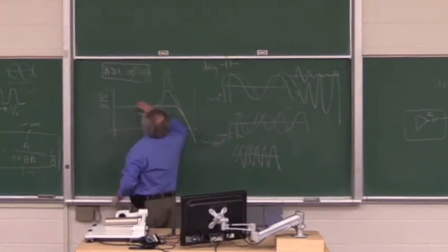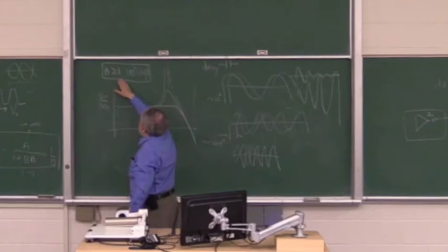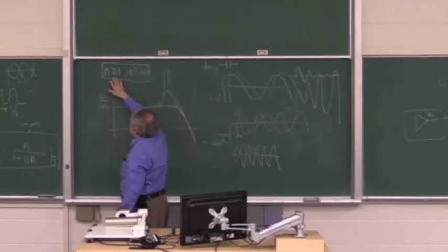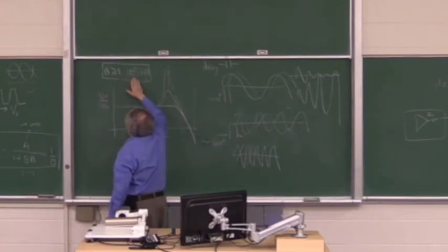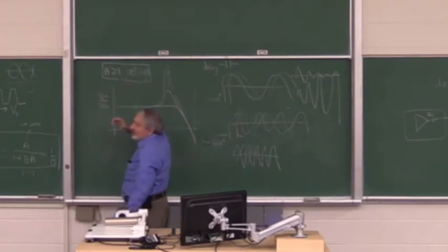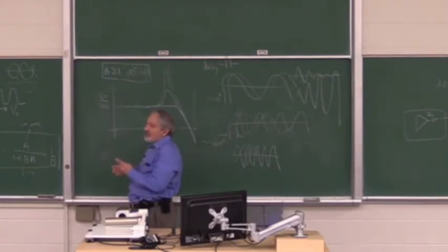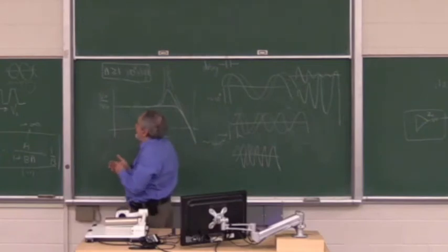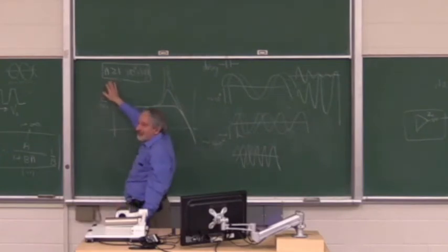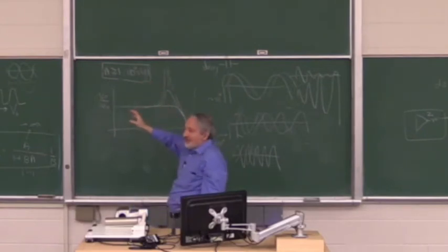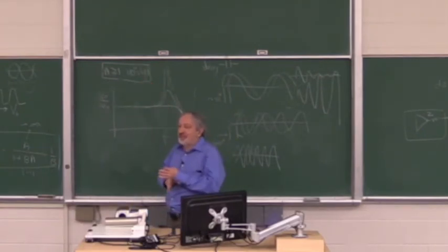So anything above that, if A is bigger, or even if A is much bigger than 1 and the phase shift is less than 180 degrees, it can start oscillating. Okay? But this is the threshold condition of oscillation. Certainly nothing can oscillate if gain is smaller than 1. So this is a very good rule to remember, the threshold of oscillation in servo systems.